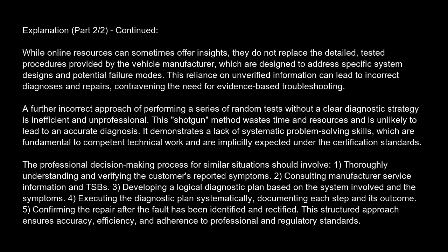Thoroughly understanding and verifying the customer's reported symptoms. 2. Consulting manufacturer service information and TSBs. 3. Developing a logical diagnostic plan based on the system involved and the symptoms. 4. Executing the diagnostic plan systematically, documenting each step and its outcome. 5. Confirming the repair after the fault has been identified and rectified. This structured approach ensures accuracy, efficiency, and adherence to professional and regulatory standards.